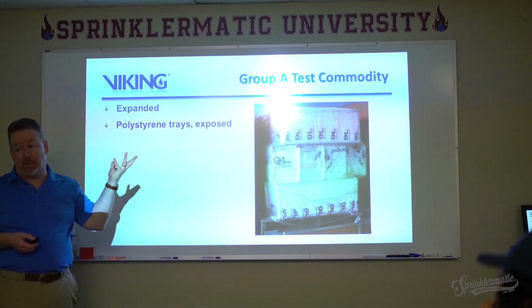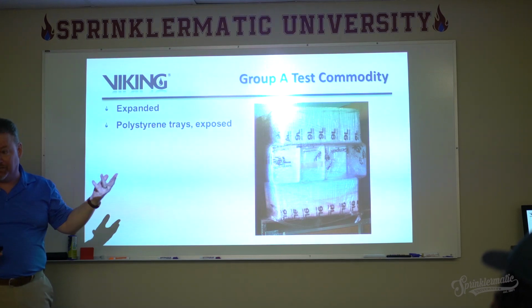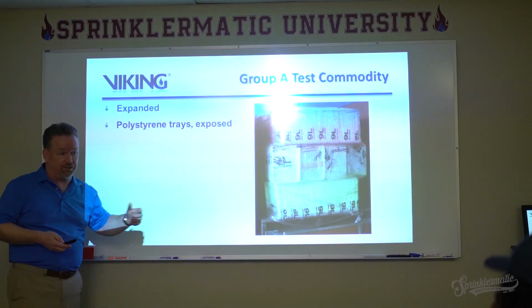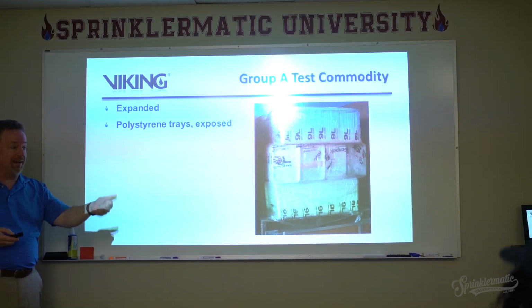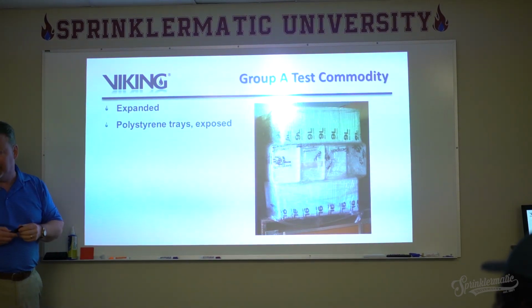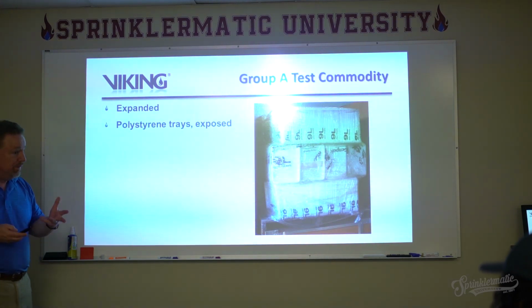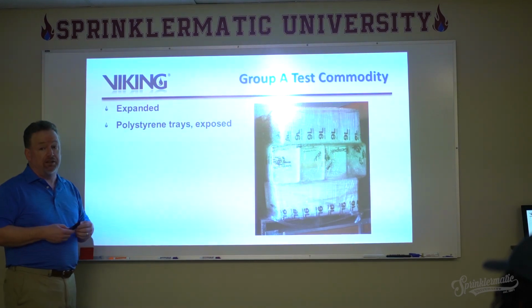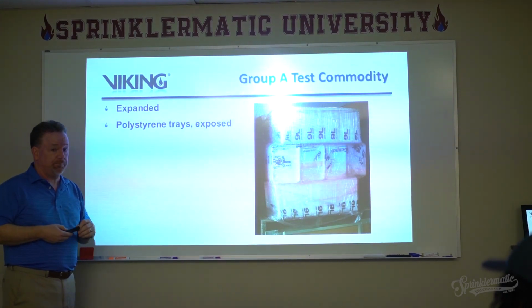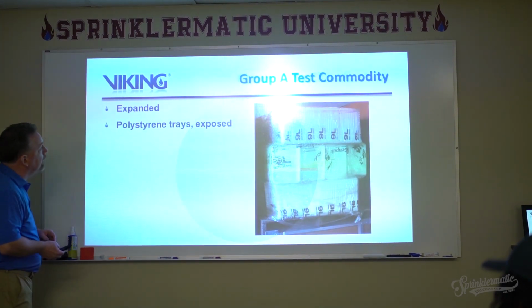These are probably the biggest commodity challenge. In fact, they are the biggest commodity challenge as far as protection is concerned, because the plastic burns really well, and it's infused with air, so it's got a natural supply. So we wind up with some pretty serious fires here and a big challenge for our sprinkler system.